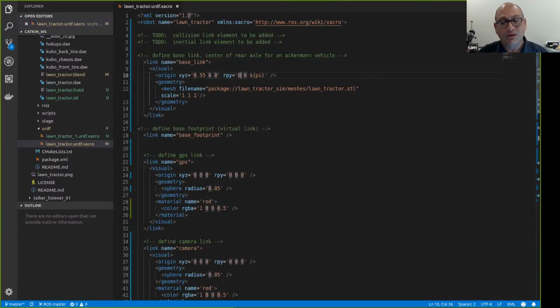Again, this is very important when you do it in Gazebo, because Gazebo is really finicky. If you're simulating physics, it really sees where your link is placed, because it treats that as where the whole mass is located, like the whole body weight.